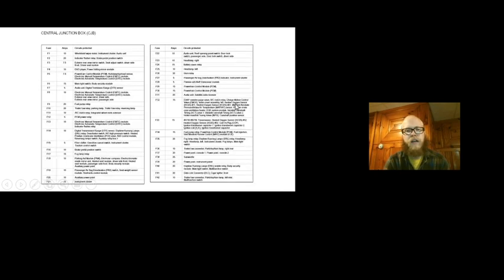It's nice to know where the fuses are, like what the designation is, F22, 23, 24, 25, and then we can go and look and see what they actually are there for. So like this F22 should be a 10 amp fuse, and it's there for the audio unit, roof opening panel switch, door lock switch, passenger side, door lock switch, driver side. So that one fuse is actually acting as the circuit protection for multiple different circuits.